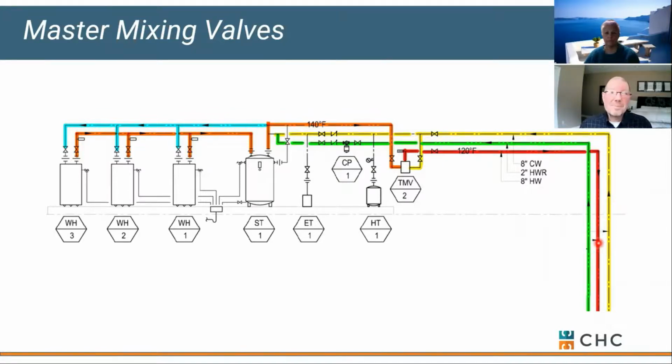Now, everybody in the apartment go to sleep. It's 2 in the morning. Everybody's in fetal position, snoozing away. In that case, it's a closed loop system. There is no city water flowing because nobody's taking a shower or washing their hands or doing laundry. They're all sleeping. So this tempered water line that goes down through our riser starts to cool off. It gives up some heat, losing it to insulation and ambient.